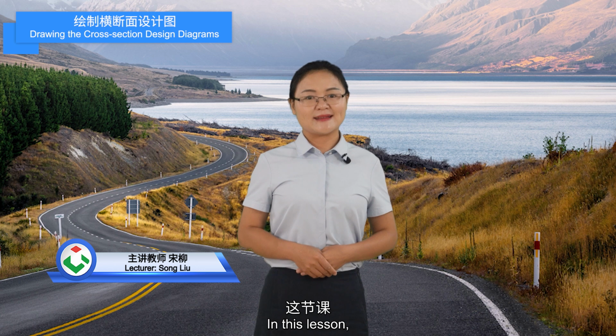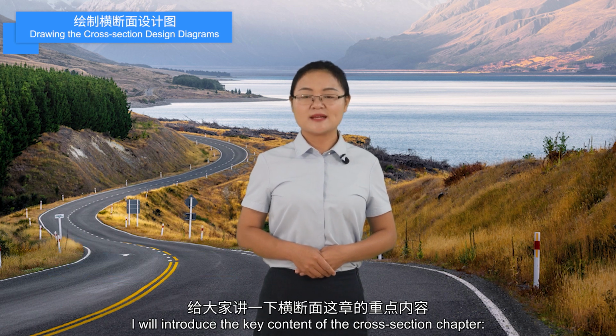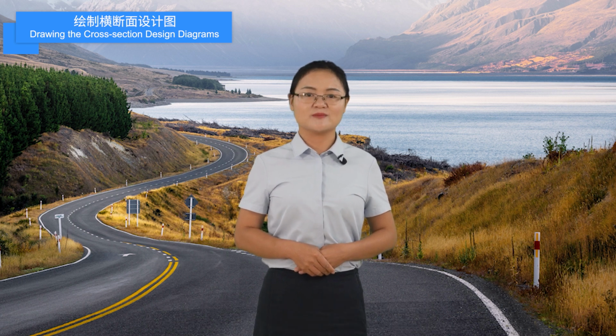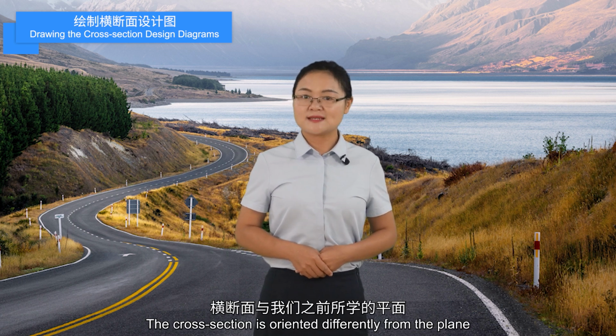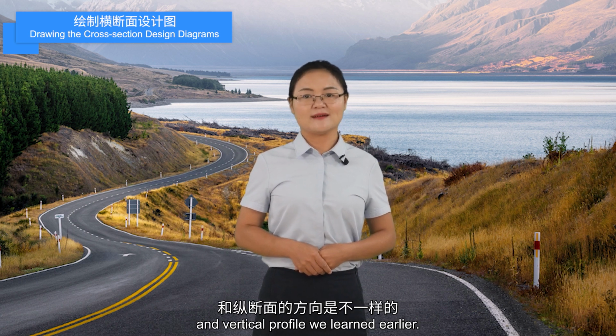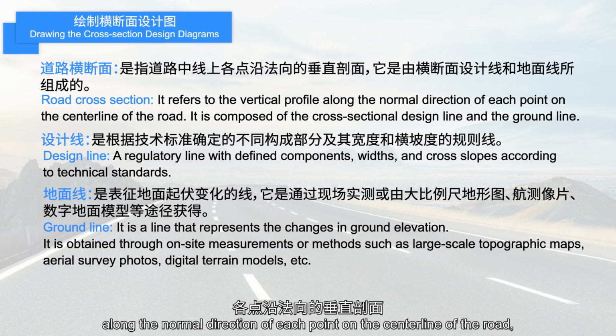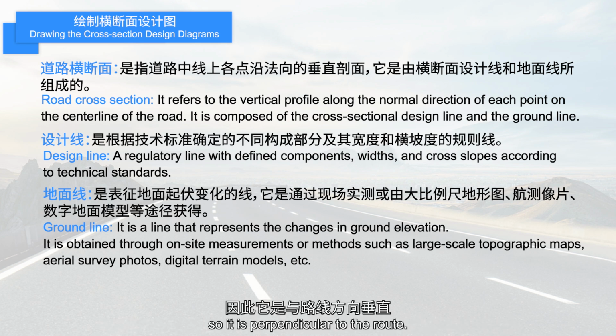In this lesson, I will introduce the key content of the cross-section chapter: how to draw a standard cross-section design diagram. The cross-section is oriented differently from the plane and vertical profile we learned earlier. A cross-section is a vertical profile along the normal direction of each point on the center line of the road. So, it is perpendicular to the road.